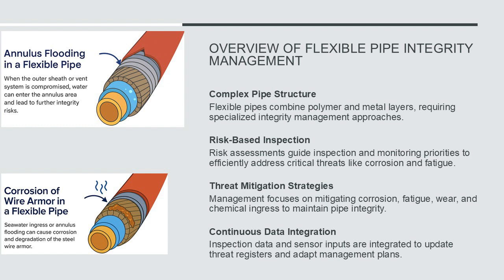The ultimate objectives are to prevent loss of containment, maintain structural capacity, and achieve ALARP, as low as reasonably practicable, risk levels. By integrating data from inspections, sensors, and operational records, integrity teams can continuously update threat registers and adapt plans to evolving conditions. This proactive strategy not only safeguards assets but also optimizes operational uptime and reduces costly interventions.